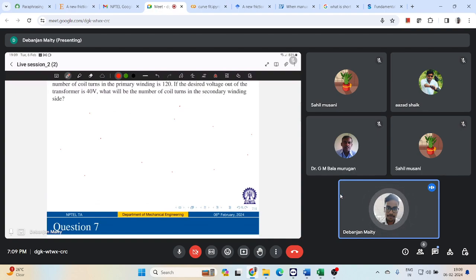So AC is a popular choice for the fact that it uses some simple and inexpensive power unit. So introducing AC leads to a complication, because unless you provide some special steps, the arc will extinguish on zero crossing, right? The current will always have some fluctuations like this. So this is my zero crossing. Until and unless you provide some special steps, that arc can extinguish.